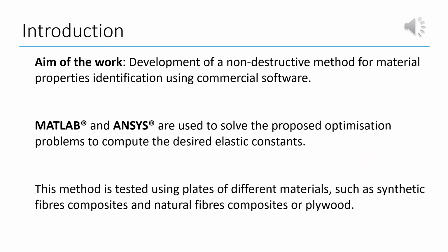With the constant development of new composite materials and the variability that occurs in the manufacturing process inherent to these materials, methods are needed to easily determine the elastic constants of composite materials. In this work, a non-destructive method for identification of composite material properties, using commercial software, is presented. MATLAB and ANSYS are integrated to solve the proposed optimization problems. This method is tested using plates of different materials such as glass fibers, wood fibers, and plywood.